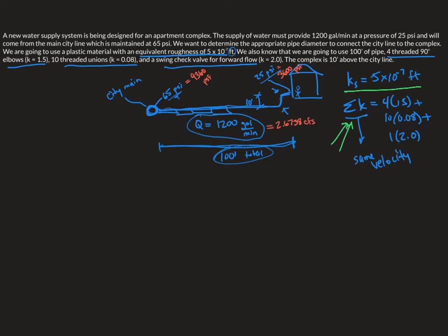And if we're dealing with the Moody diagram and we need to get f, then, and I'm just logically working this backwards, on the Moody diagram we're going to need to be able to get the relative roughness, which we usually write as epsilon equals Ks on D. So that's normally this axis. And then on this axis is the Reynolds number. Reynolds number equals VD on nu. Note, in this particular problem, we do not have D.